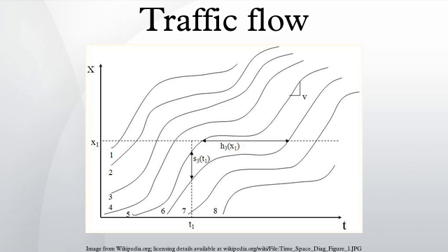At some location X1 before the bottleneck, the arrivals of vehicles follow a regular N-curve. If the bottleneck is absent, the departure rate of vehicles at location X2 is essentially the same as the arrival rate at X1 at some later time. However, due to the bottleneck, the system at location X2 is now only able to have a departure rate of μ. When graphing this scenario, essentially we have the same situation as in Figure 9, where the arrival curve of vehicles is N1, the departure curve of vehicles absent the bottleneck is N2, and the limited departure curve of vehicles given the bottleneck is NA2.